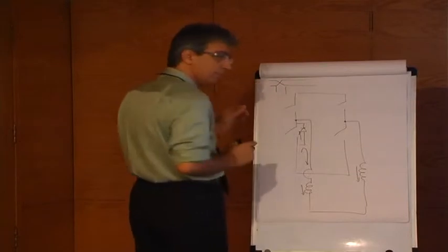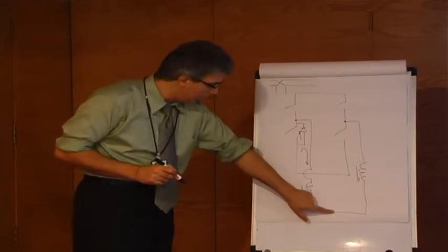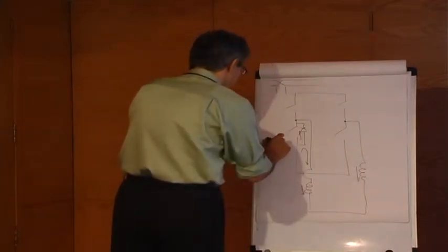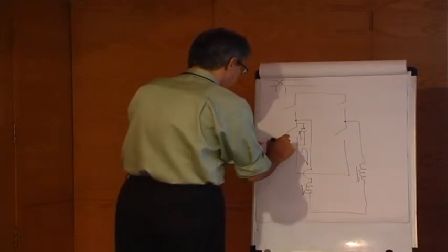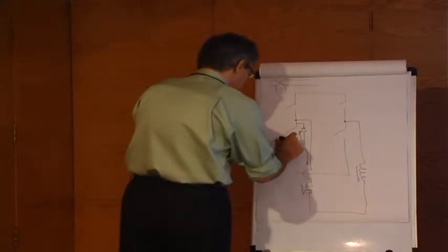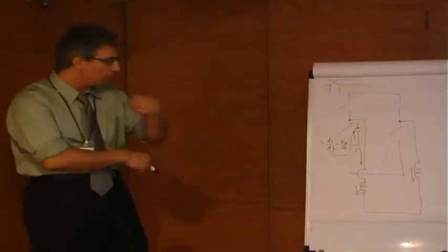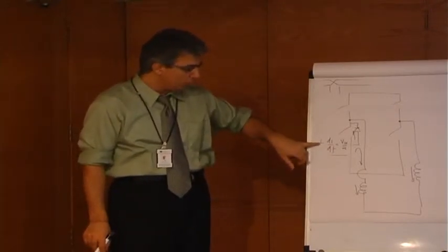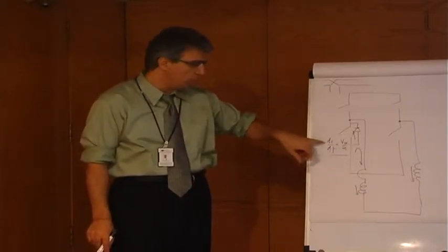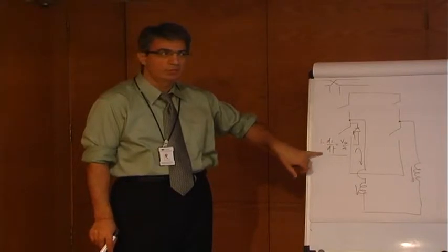Now this time period here is essentially, when this is going down, the inductor voltage here is essentially L di by dt. And this is equal to, if you take the neutral voltage to be half of the supply voltage, let's say this is V dc by 2. So that's the equation. Now, if you have this equation, delta I by delta t is pretty much dependent upon the voltage and the inductance, and of course the value of the current. What is the value of the current?